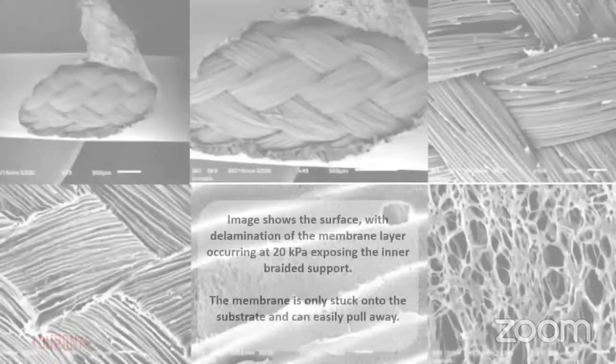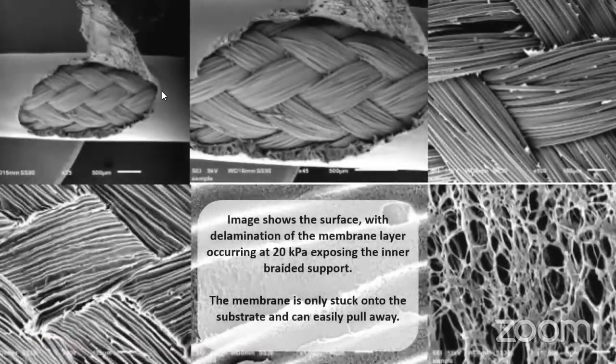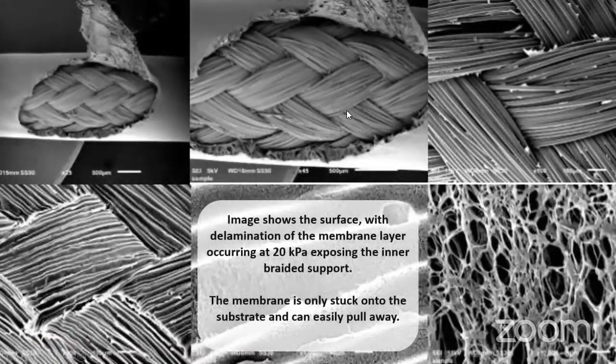This is a very close shot of a two-layered membrane, wherein you have a braided structure and a membrane filter area that is laminated over it. When there is high pressure and air-based cleaning is already happening, this structure is likely to get peeled off.